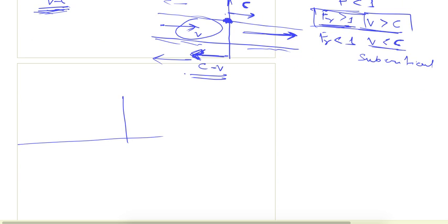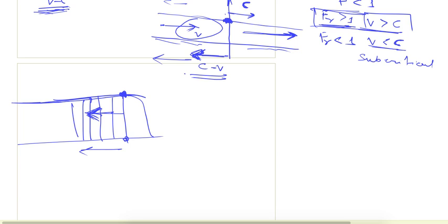If I'm making a dam here, whatever the flow is coming, it was there at uniform depth, but now because of this structure, this depth will increase. Because this is in the subcritical zone, this depth is increasing. If I know the depth of flow here, I can calculate the depth in this direction. So I'm starting from a downstream point and moving on the upstream. So downstream is the control section for subcritical flow.